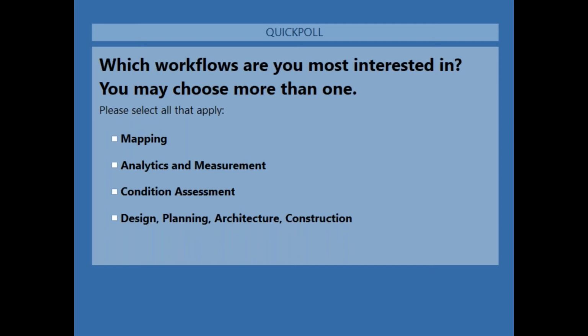And while you're taking a poll, there was one quick question. What is the starting point of the data input into Skyline? Is pre-processing done in Skyline, or is it post-processing? Skyline typically will take the fairly raw data from the sensors. They do need to be geolocated, but Skyline will take in the raw data from the sensors, and it does all of the processing, all of the matching, tie point creations, and then it builds your 2D and 3D products. And Itai can elaborate on that a little bit more.